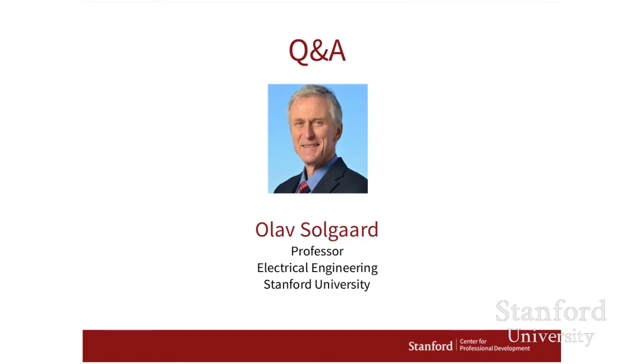So the next question goes to this thing about integration. Is it possible to etch MEMS sensors on the same silicon die as an integrated circuit? And that is possible, and there are many strong examples of that, and I keep bringing up this digital light processing technology of Texas Instruments. I think that's a tour de force in technology development. It has electronics underneath, and it has built MEMS on top. So that's definitely one example of that. And there are several other companies that have done the same thing.